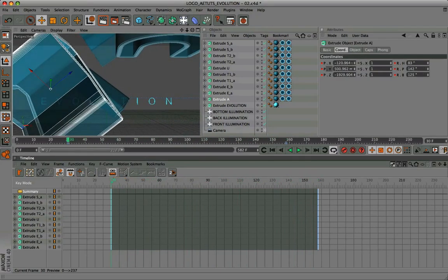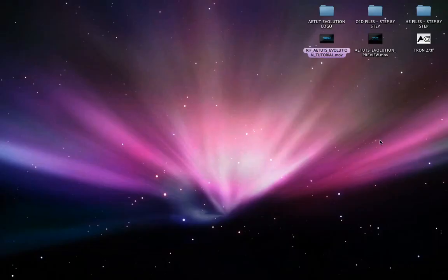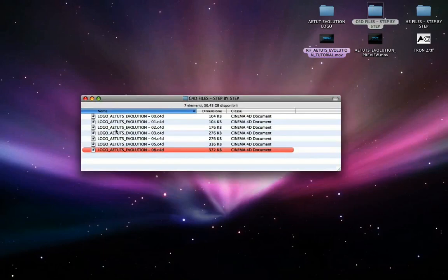See, this animation moves all the letters and parts of letters together. Obviously, to make things more interesting, but above all more casual, we must ensure that in the interval between frames 30 and 158, each letter or part of letters moves with different entry times. We must make the overall effect more random. I assure you that the end result will be truly fabulous. If you had difficulty in this step, you can always open file number 03 in the Cinema 4D folder.